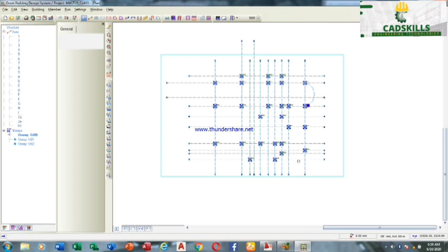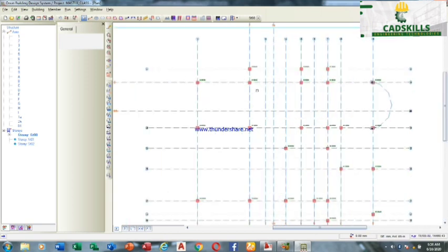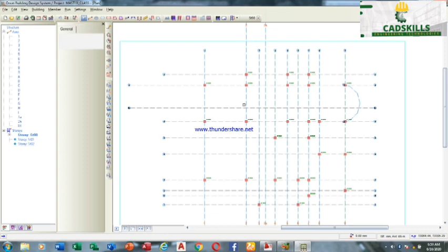It added the load that is coming on this building and divided it equally to every column. Very, very dangerous. So I don't encourage that. So you don't design all. You design one by one so that you can point out the load coming on this particular column, so as to know the choice and the area provision of the reinforcement, and the section also, very, very important.